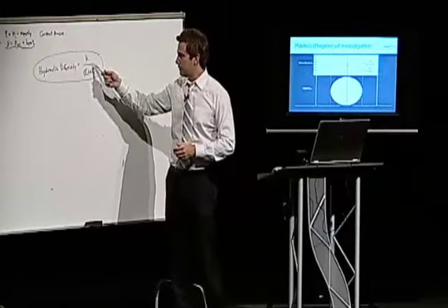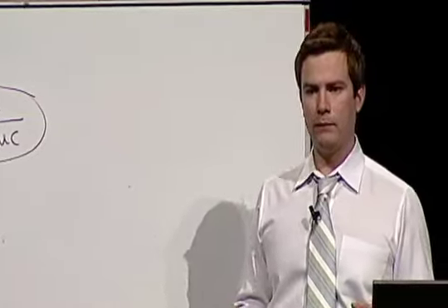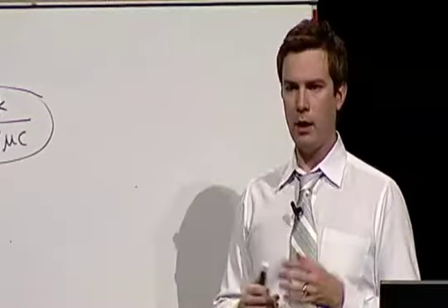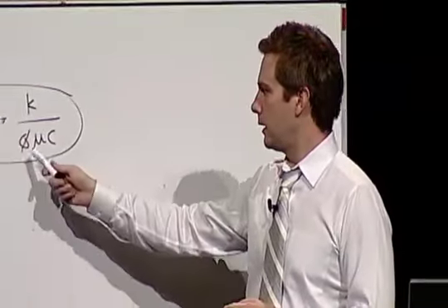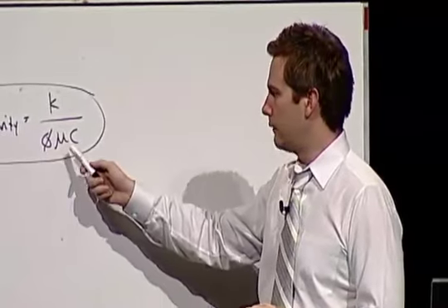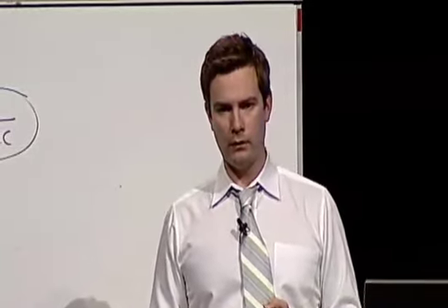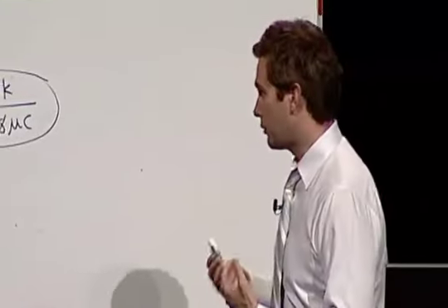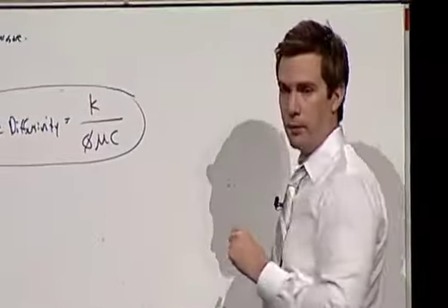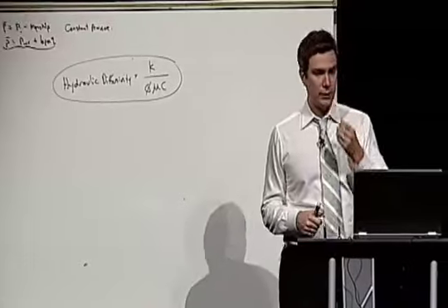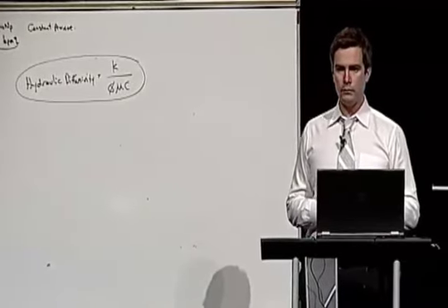The only thing that matters in here is what's actually in the reservoir. So permeability is a function of the rock property itself, as is porosity. Viscosity and compressibility are functions of the fluid that sit inside the reservoir. So the hydraulic diffusivity is really an in situ property. And that's what's going to control the radius of investigation.